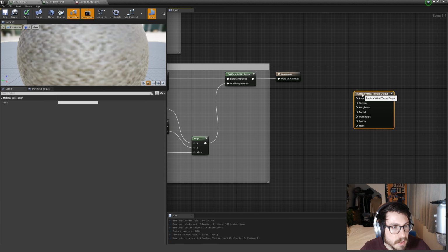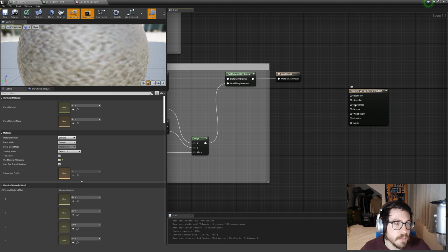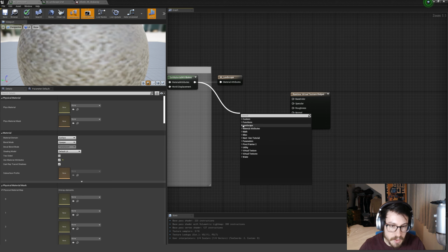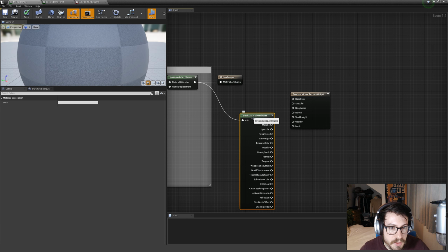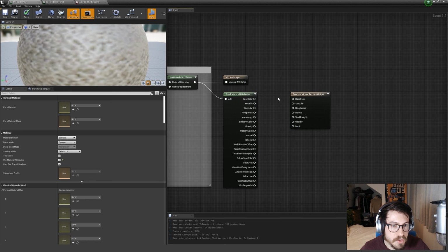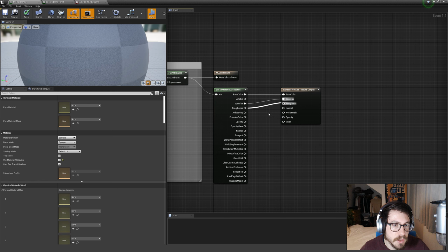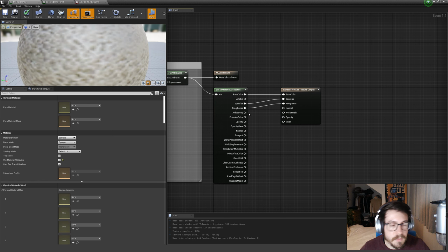And in here, we will plug in all the attributes that we need. So we need to get the attributes that we have here and just break material attributes to get all of them. And let's just get the ones over that we want. Base color. I mean, metallic, there is no slot for it, so we don't have any metallic in our scene, in our environment, so that is no problem at all. Otherwise, you can hack it in, for example, by putting the metallic into a mask or something like that, or into the opacity, and do it that way. It's a bit of a hack, but it should work.